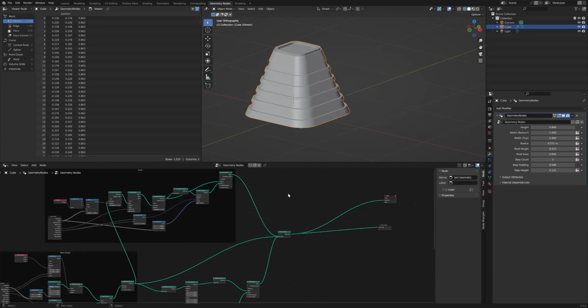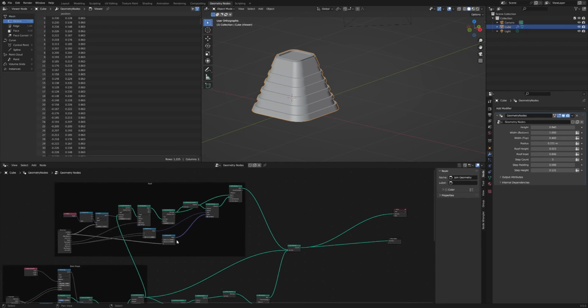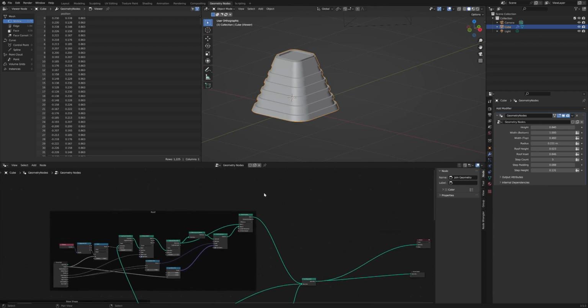So for our last piece of geometry that we're going to modify on our shape, we're going to reuse a lot of the same kind of functionality and features that we've done before. Build a cube, modify that cube, set some parameters on the right hand side, and then use that as a boolean to cut out further shapes from this. So the first thing we're going to do, as mentioned and as we've done before, is use a cube. We're also going to use mesh boolean.